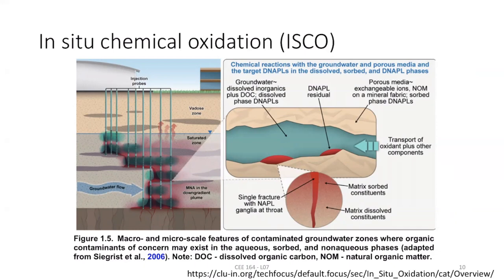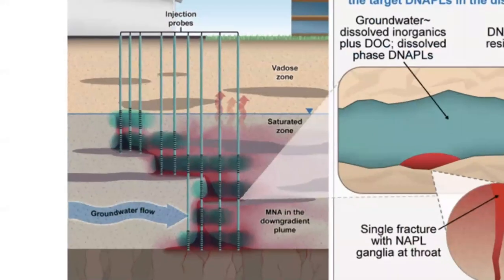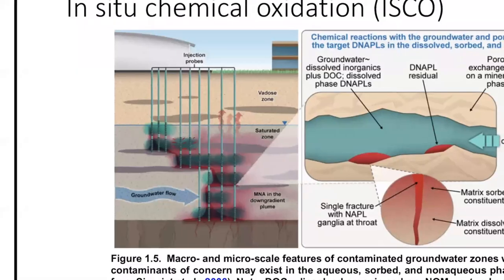As you see over here, there are these wells. These wells have an opening over here, so you just pressurize them. The first thing is to find out where the pollutants are so that you can actually put the well at that location. So that's the design challenge, to identify the locations, because you don't want to inject oxidants in a non-contaminated area. So once you know, you are just pumping it.